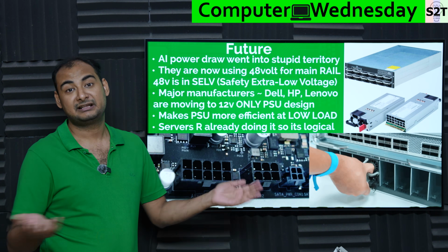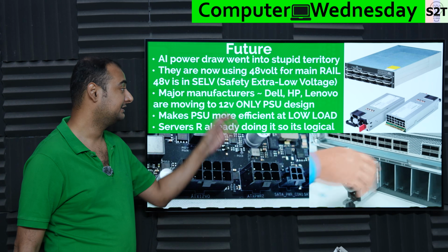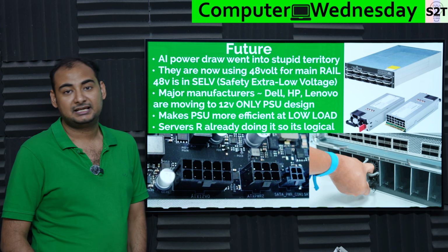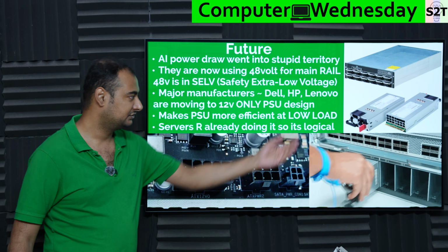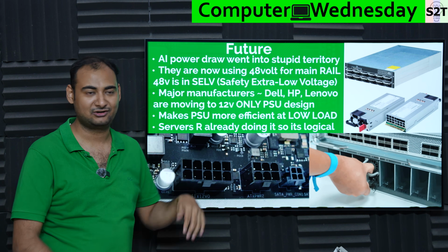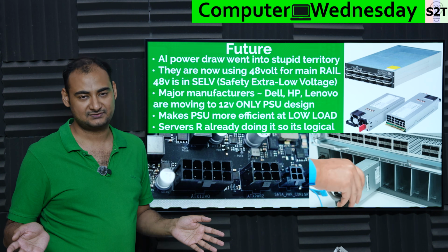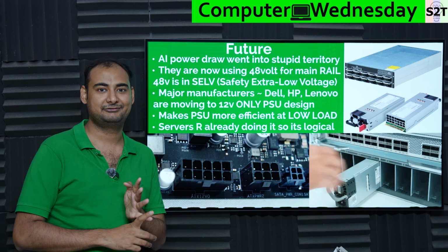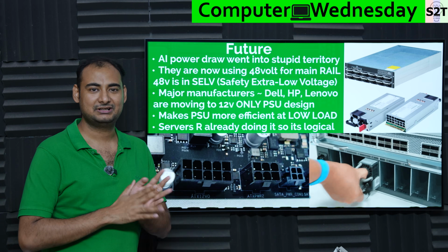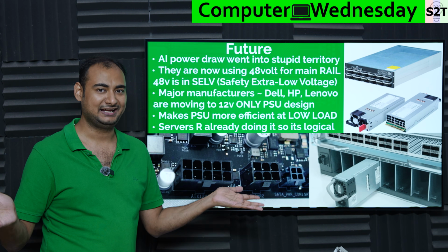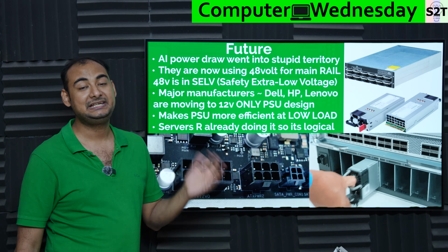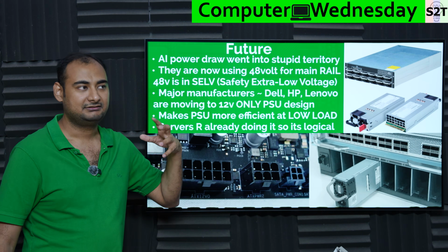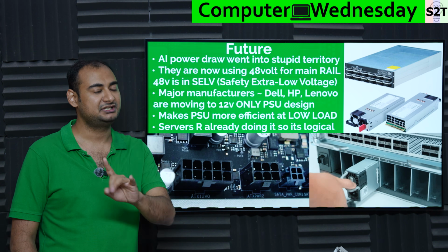But what about major manufacturers on the desktop environment? Dell, HP, Lenovo, they are going to server, exactly like how Pentium did in the long ago. It's like throw away all other useless voltage. You have 3.3 volt, 5 volt, negative 3.3 volt, negative 5 volt, standby voltage load, throw all of those away. It's like, well, why? Well, the idea is PSU, as in the power supply unit, can be very efficient if it's only designed for 1 voltage.